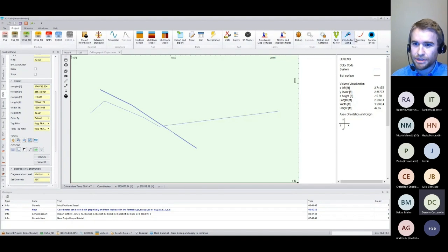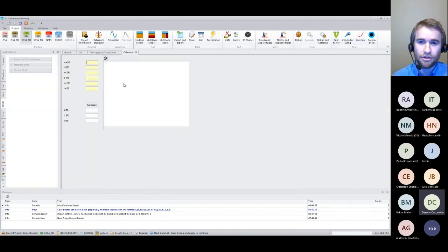I do need to shift my transmission line up into the air, but I also need to consider that catenary curve or that sag characteristic that we looked at. So I will place this. We'll use our catenary curve process. So we'll say this is starting at 85 feet as its elevation, goes out 500 feet, sags to 45 feet, then increases to 1,000 feet in its path, and then we'll bring that back up to 85-foot elevation.